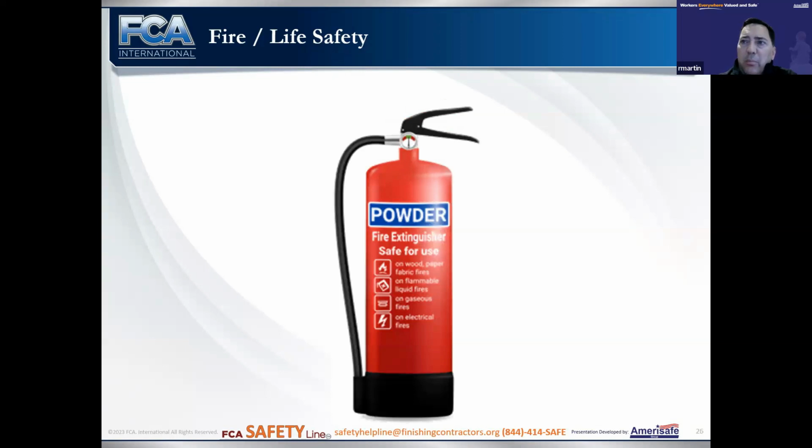And there's the one we want, the powder fire extinguisher. Note it says safe for use on wood, paper, fabric fires, on flammable liquids fires, on gas fires, and on electrical fires. If you spray this on something electric that's running and on fire, you won't get an arc back at you. This will just start putting the burning material out.